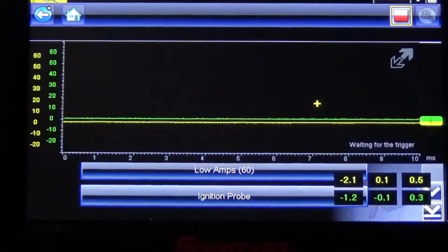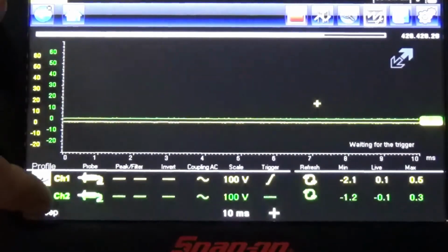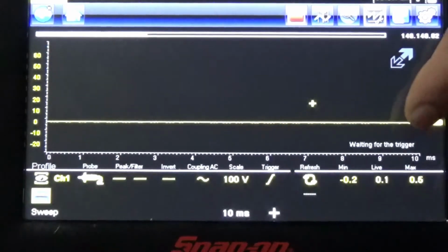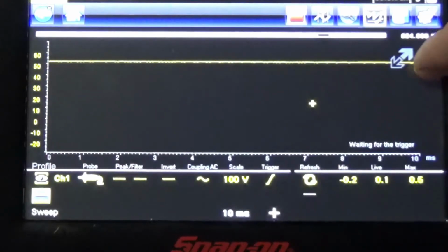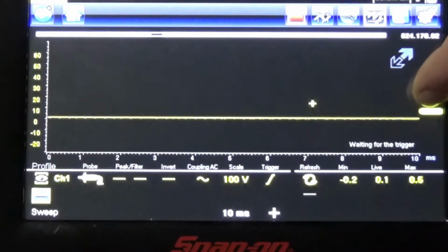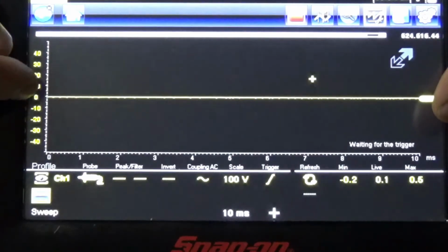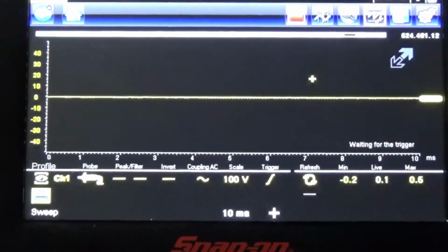It's going to boot up. Now, from here, since we only watch one channel, we just click on the little eye, and it's going to take away channel 2. And this is how you move your baseline. Now when your baseline moves, your 0 on everything on this side is going to move. So basically you're going to have the same thing as on the Hantek.